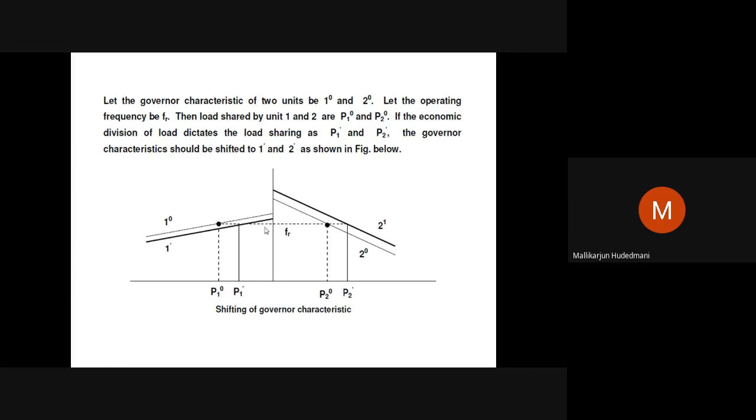If governors were not there, I am quite sure the frequency of this will be different, and the frequency of this will be different. They cannot be in parallel. Therefore, in parallel operation, when the machines are put in a station, a common frequency has to be managed. Their regulations have to be kept in mind. This shows another case study of how a governor is in play to manage the mechanical increment or decrement of input to the turbine for contingent changes in the load, to address deviation of frequency to 0.